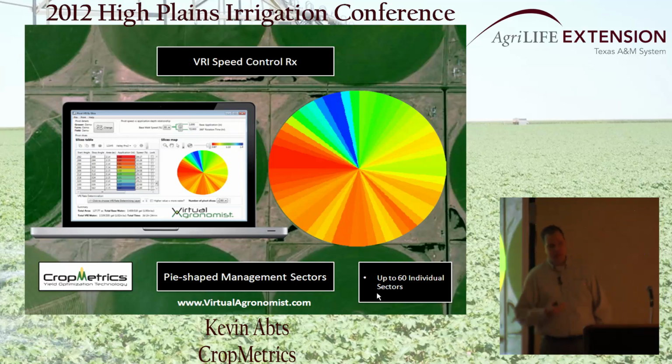With our partnership with Valley, of course, all Valley computer main panels would have the capability to load up to 60 sector prescriptions with the new software upgrade. Also, the PivotTrack GPS, the newer GPS devices, can be installed on the end, and they also have the capability to do the 60-sector speed control. So what that means is, for those of you that may already have PivotTrack or are upgrading to a PivotTrack GPS, you have basically VRI-ready capabilities on that system. And we can do this once we have that EM or EC data collected.